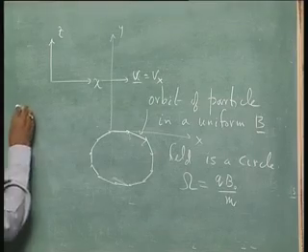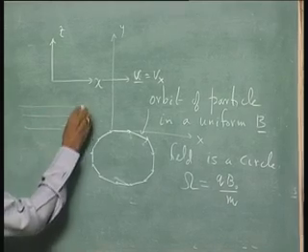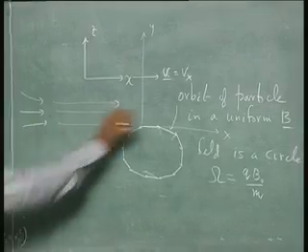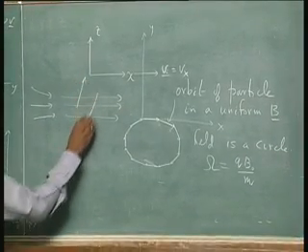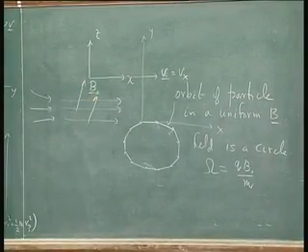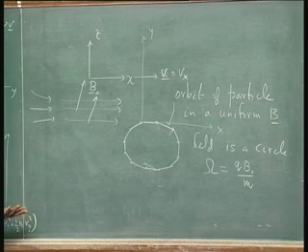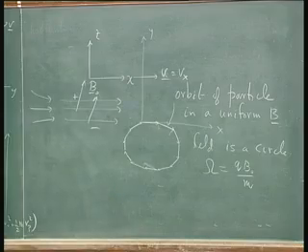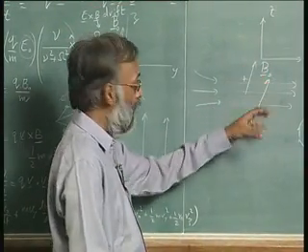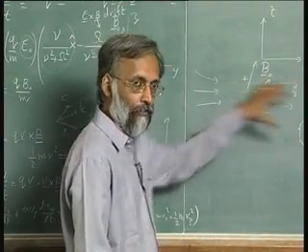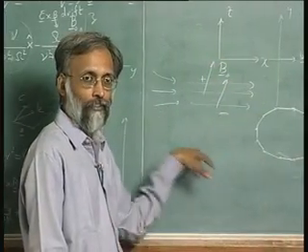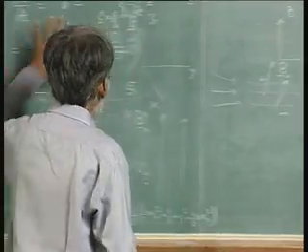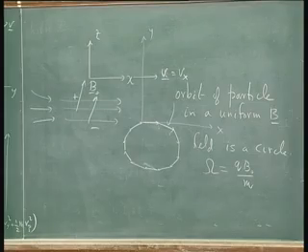So if I have some kind of pump, which is forcing fluid through a region where there is magnetic field, and if this fluid is a charged fluid, then automatically an electric field will develop, and this electric field can extract the energy of the flow and convert it to electrical energy. This is nothing but MHD power generation. It is the same equation, it is just how you tilt your head and look at it.